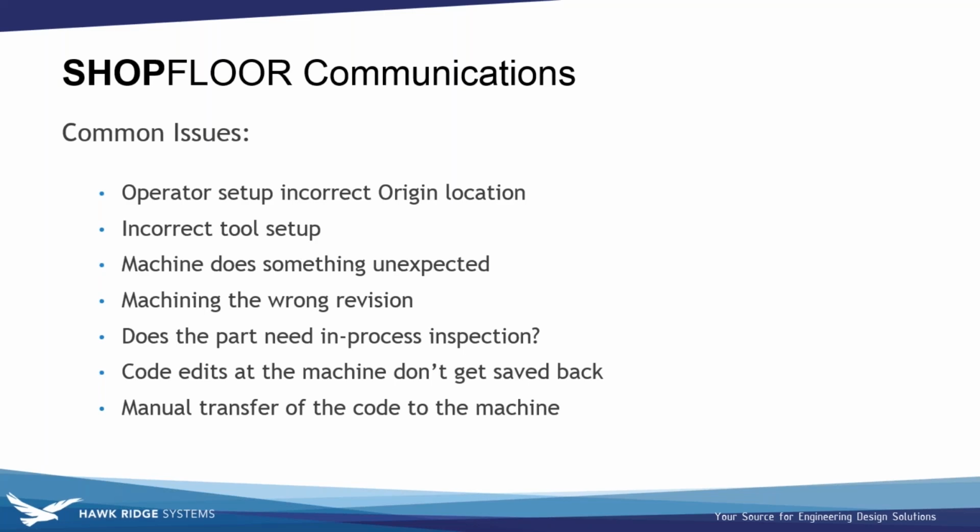Incorrect tool setup. Maybe the operator didn't know exactly what tool length or tool protrusion to set up in the machine. What do I need for that particular job? The last thing you want to do is go crashing that machine because of the tooling not matching up. So giving them the right information for tool lengths and tool reach and things like that.